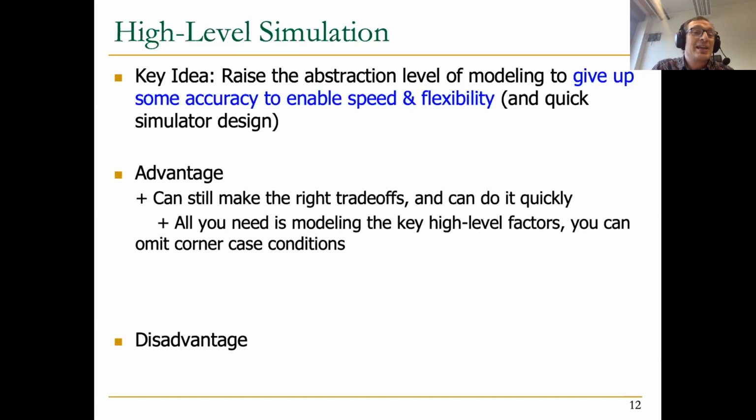Well, you could actually. You could start with very high-level C blocks, and then you say, okay, I'm going to model this, model that, model that. And over time, you transition your C-level simulator to RTL simulator part by part. Right? Of course, this requires even better software engineering. Basically, some part of your simulator can be modeled with RTL. Some part of your simulator can still be modeled in C. Some other parts can be modeled in Python, etc. And that way, you can actually focus on the parts that you really care about in the design of your processor potentially.